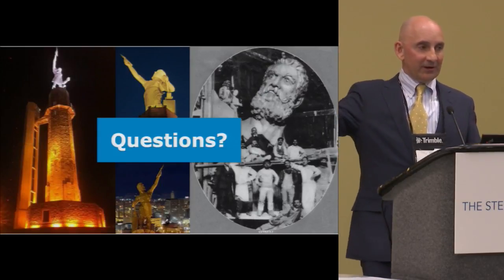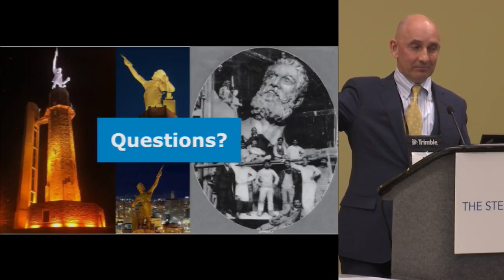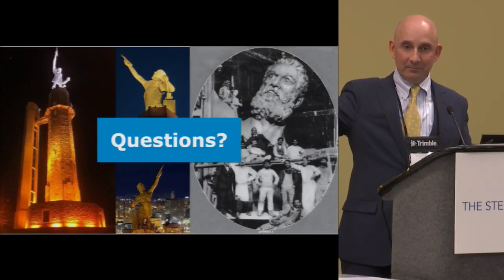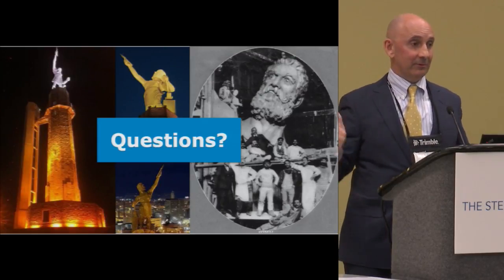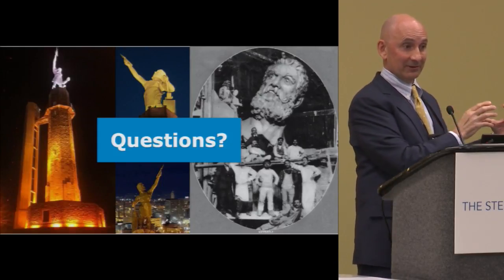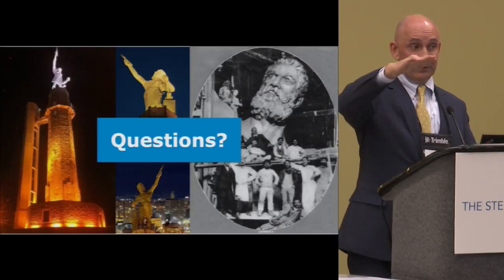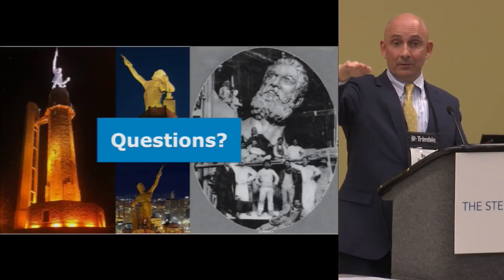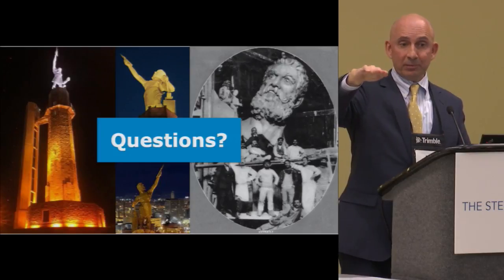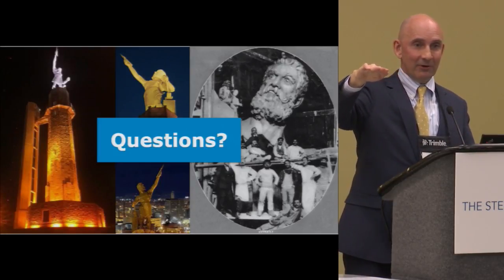So if you can somehow get this double coped beam to behave plastically, in other words, you would make your k over r less than 25 so that you don't have stability effects and compression, and then you would have to be on that horizontal plateau where your moment is equal to Mp, and that's a pretty high bar.